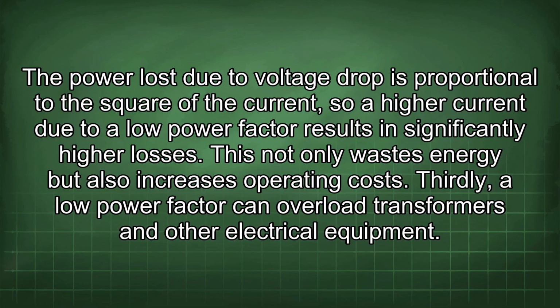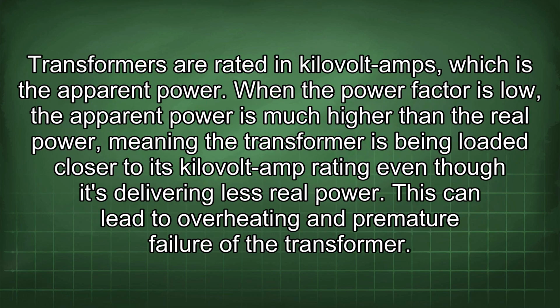Thirdly, a low power factor can overload transformers and other electrical equipment. Transformers are rated in kilovolt amps, which is the apparent power. When the power factor is low, the apparent power is much higher than the real power, meaning the transformer is being loaded closer to its kilovolt amp rating even though it's delivering less real power. This can lead to overheating and premature failure of the transformer.